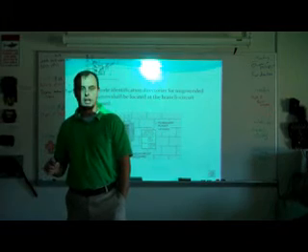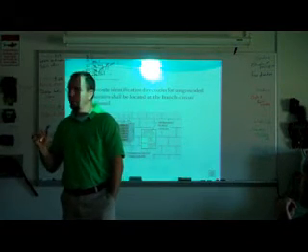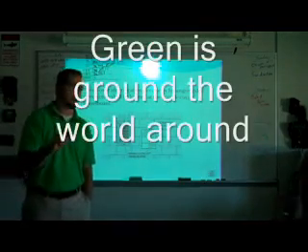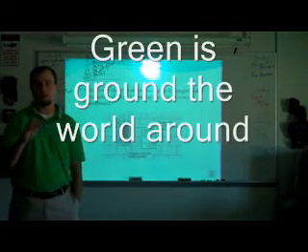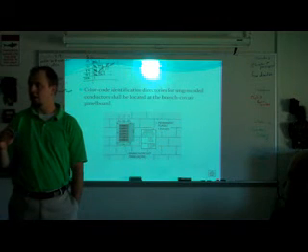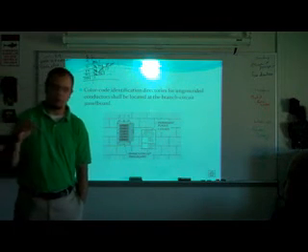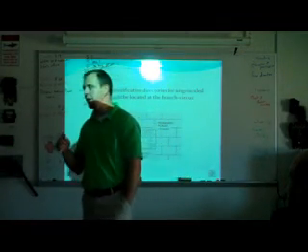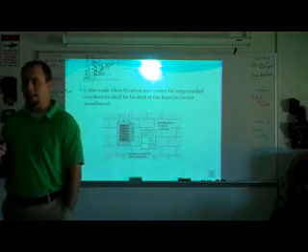I was like, man, what the heck? As an electrician, you should never, ever use green for anything but a ground. For DC, there are no codes for conductor identification, so you should always stay vigilant with that. Never run a green, because that really threw me off. That did not make any sense.